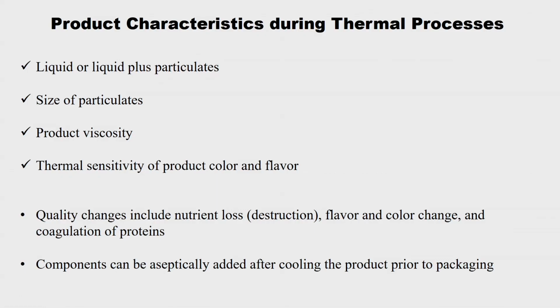Okay, so these are all the major equipments. Now we know how to design and what design criteria I need to look into while designing an aseptic equipment system. The major ones are pumps, heat exchangers, either direct or indirect type. Then there comes a holding tube and there is a surge tank, and we have also seen the static mixer, which will be used to just mix the product. Why, I will be telling in a few slides. So, what is the need and why the static mixer is kept, and also all are maintained in the sterile environment.